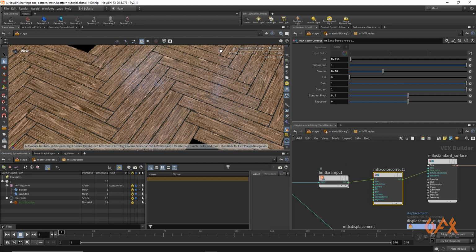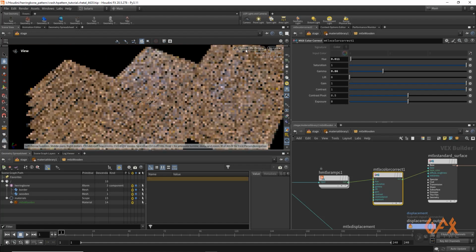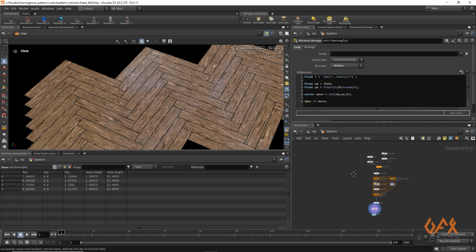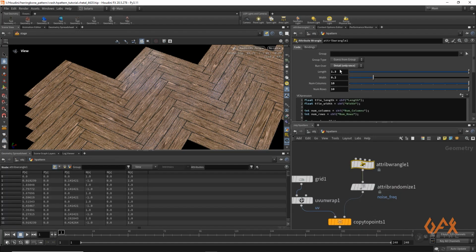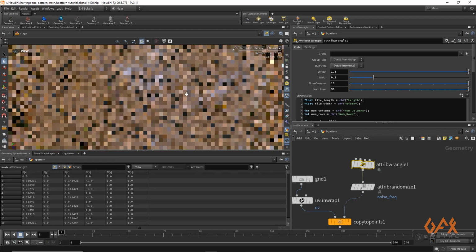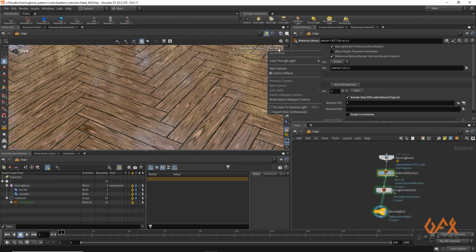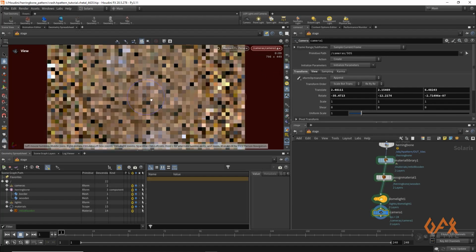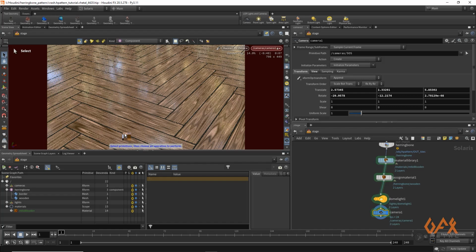Okay, so definitely I just lock this one, view, just press 1, select this attribute triangle, and it is possible that I just change this number of columns, maybe number of rows, maybe 30. And you just set your camera, like here I just create a new camera, lock that one. So that's how you can create a wooden herringbone pattern.